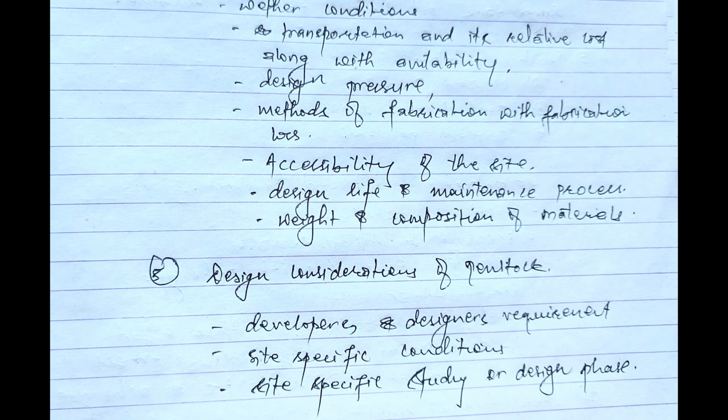Points that must be considered for site-specific requirements are land ownership or right of way of the penstock alignment, and terrain configuration of the sites, environmental resistance including the aesthetics, fish, wildlife and natural habitats, etc. And the next one is site hydrology and geology along with the soil type of the site. Another consideration for the design of penstock for site specification. And another one is applicable codes and mandatory requirements or the bylaws of the particular sites.